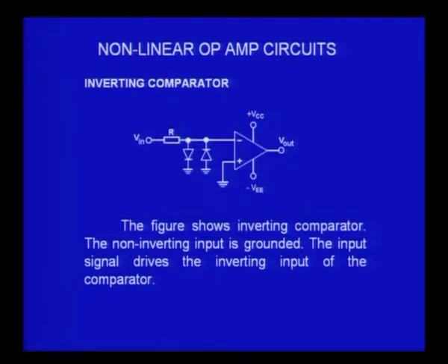That is good enough, because we have seen that, because of the open loop gain condition, this voltage cannot be different from this voltage beyond plus or minus 150 microvolts or so. And 0.7 volt, which is 700 millivolts, is a very large voltage comparatively, and therefore we will never have any occasion to go beyond 0.7 volts. So this will provide protection for the comparator, so that you will never overload the terminal beyond 0.7 volts.